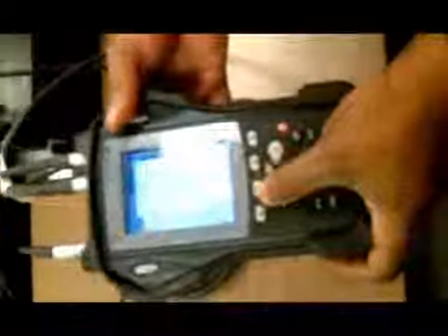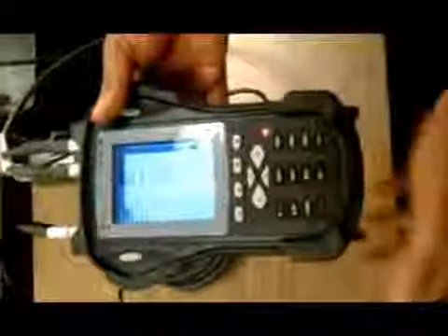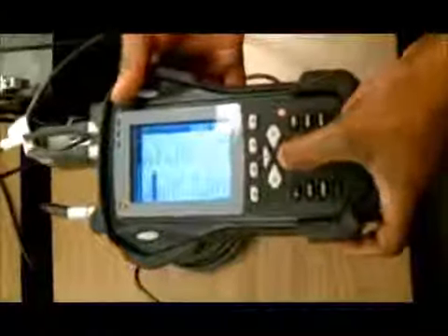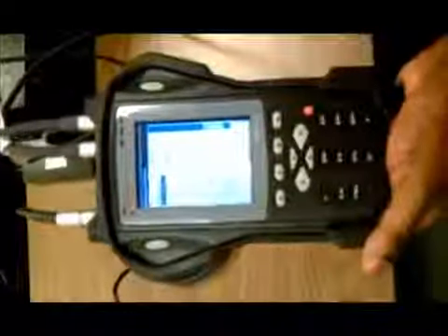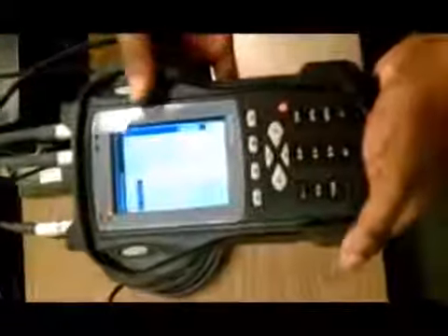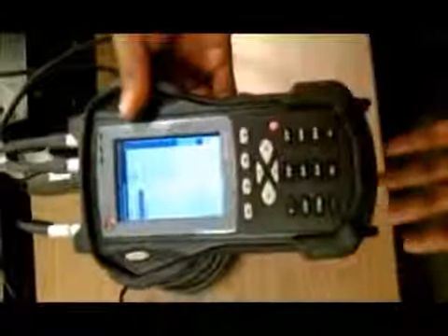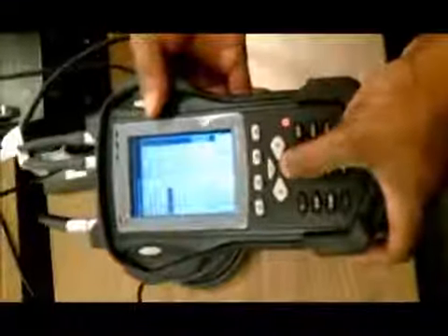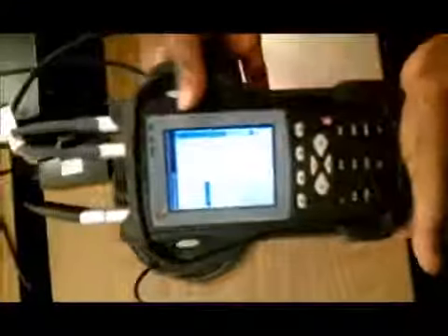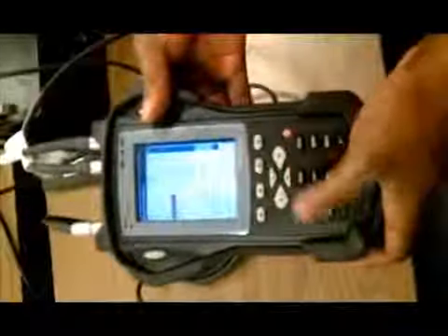So what we'll do now is hit options, which will allow us to set up the rest of it. For our detection, we want peak to peak, so we get a forward and back, the whole forward and back motion. Our solution is going to be influence coefficients because we're using the trial weight method. And what we'll do now is set up our planes. Channel 1 is going to be plane 1.